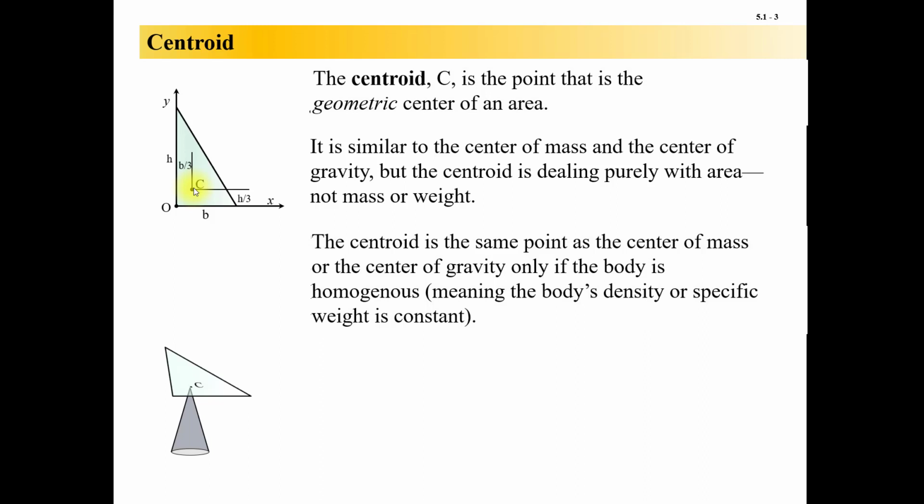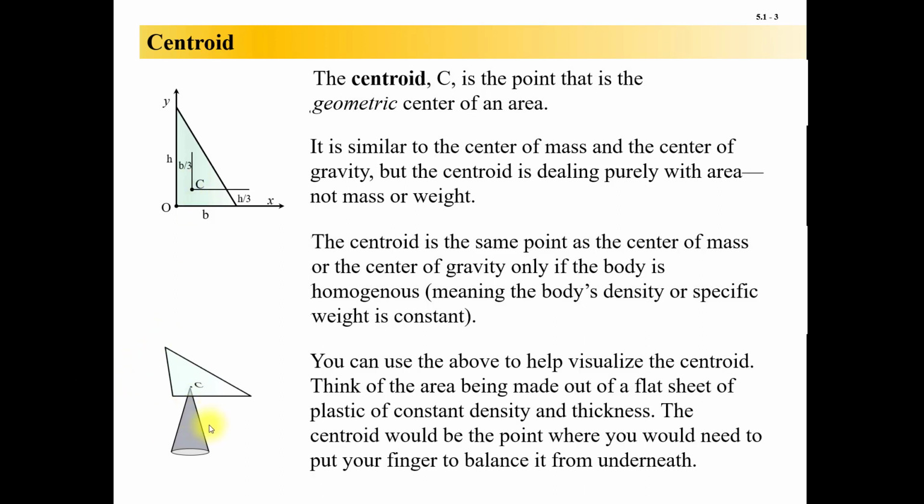So it helps to think about the centroid from the perspective of center of gravity. If you think of your areas as flat plates of constant thickness and constant material, like a steel plate or a ceramic plate or plastic plate or something, and balance it on the tip of a cone or your finger, the centroid would be that balancing point. Now, that really is a center of gravity, a center of mass type of way to visualize it. But again, if you think about it as a constant thickness, constant density, then it starts to make sense.